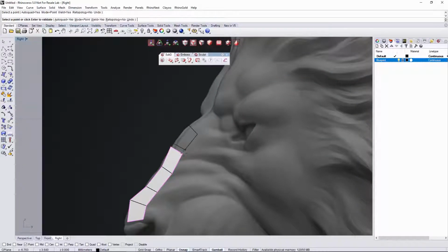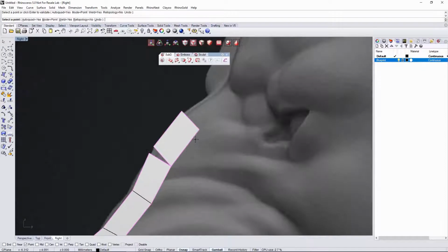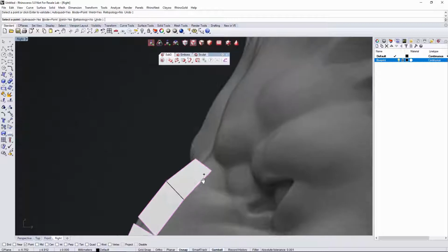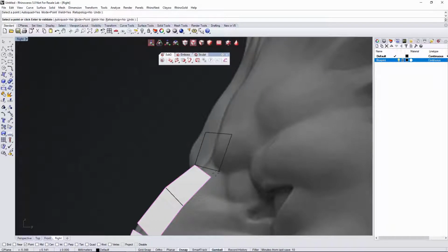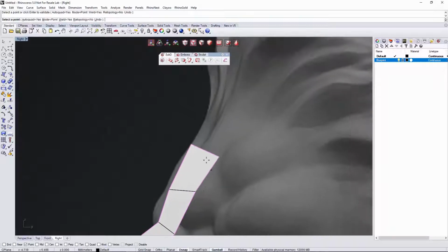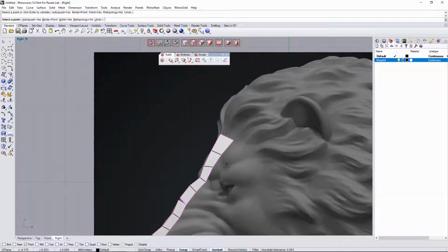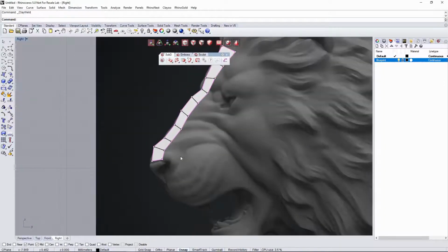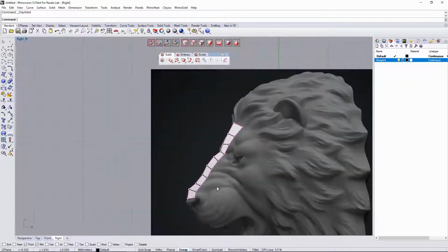Okay, and I'm going to start creating the main shape. In this case it's not touching, but it's no problem. I just misclicked the point. Okay, depending on the quality or the resolution that you want for your model, maybe you want more or less faces on this first step. So in here I'm gonna go to vertex, select those vertex, and let's go to weld. Okay. So this is gonna be the main shape.